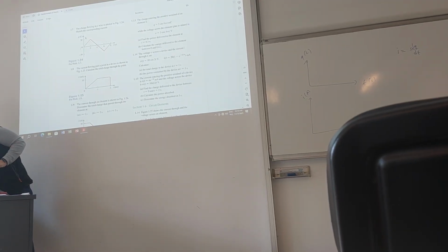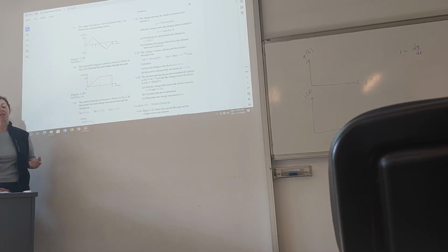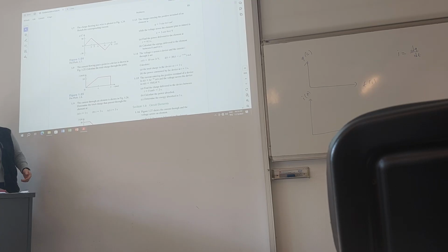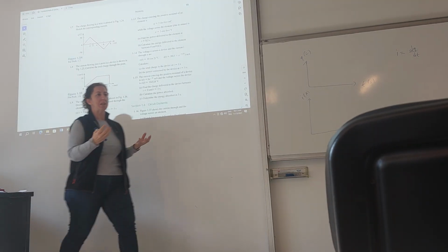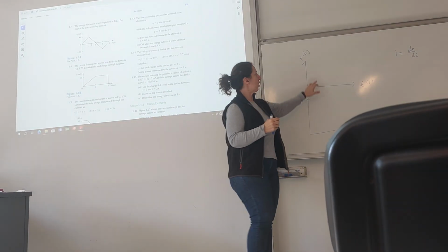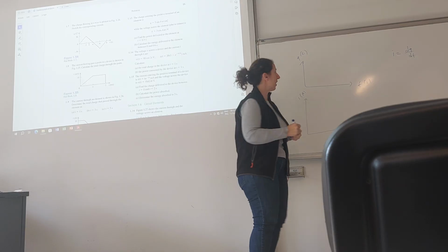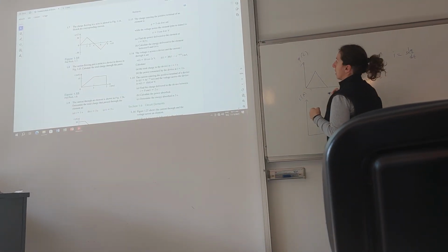In this Q-t graph, if I take the derivative for the first 2 seconds, what would you get? Slope. So slope, which is dq over dt basically, would give you the current. So if you have a Q versus t graph, you can extract the I versus t graph from there. In this case, it was, let's say, this.